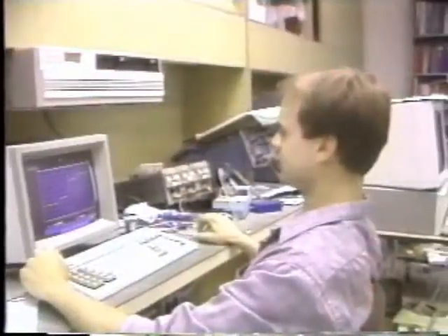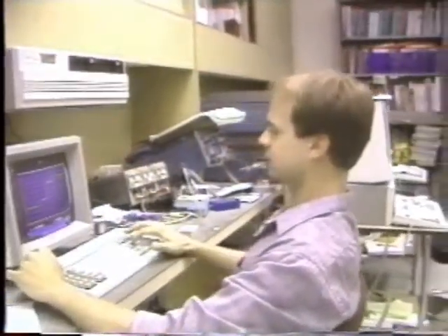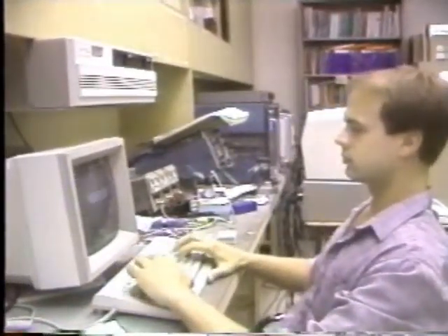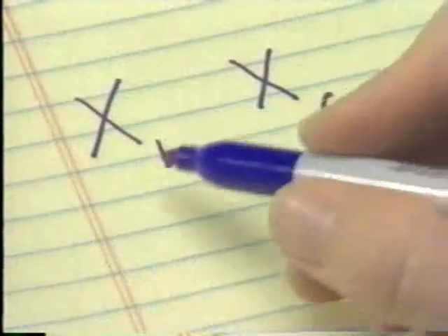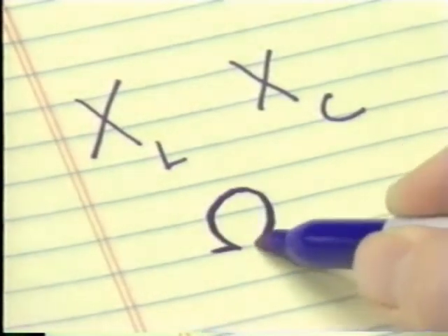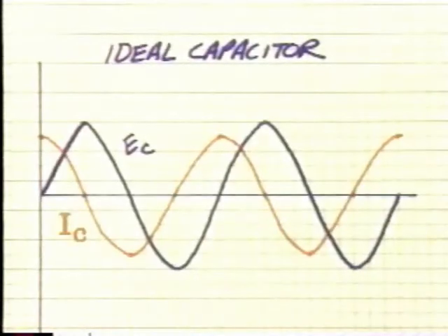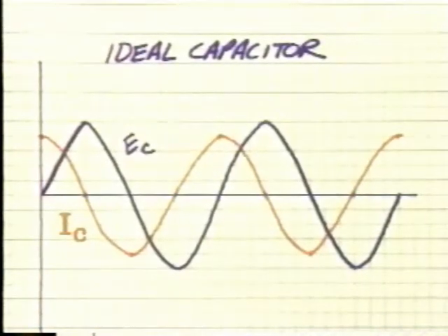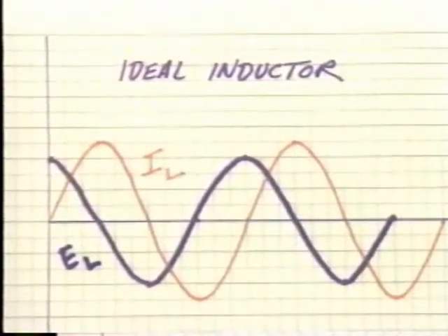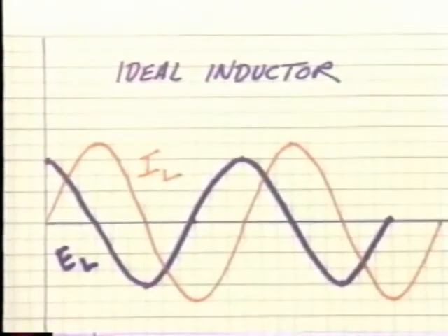It's important for you to have an understanding of these two types of reactance because when you get to AC circuits, you'll see how reactance interacts with the circuit resistance in certain predictable ways, which become a critical factor in the design of circuits. For now, keep in mind that both inductive reactance and capacitive reactance are measured in ohms, and that in the capacitor, the capacitive current leads the voltage by 90 degrees, whereas with an inductor, the inductive current lags the voltage by 90 degrees.